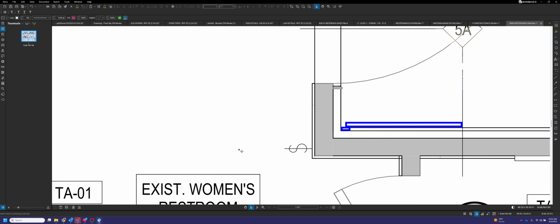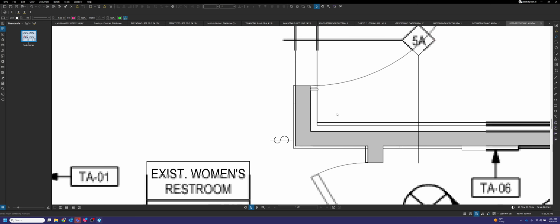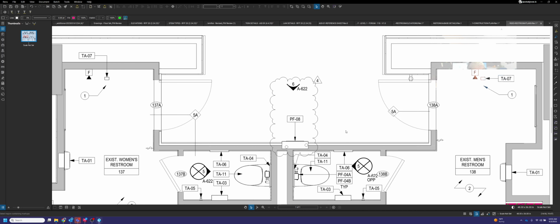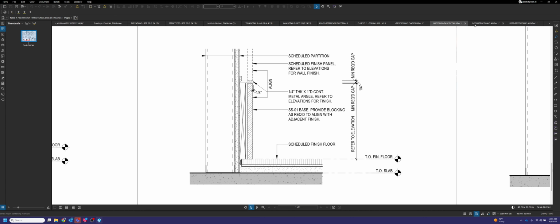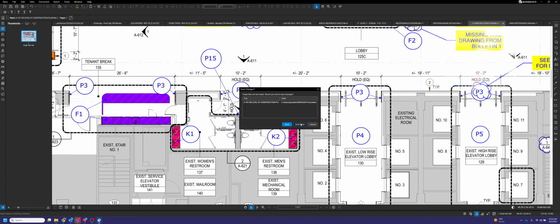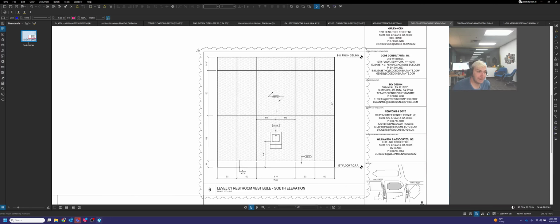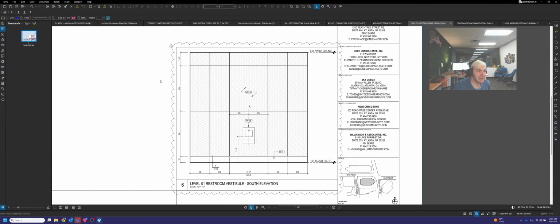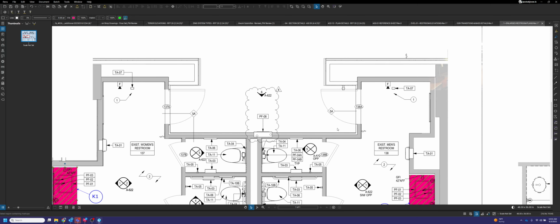Okay, so because we're using panel cleats there and we're using our full depth reveals at the corners and our 1/4 inch spline reveals between panels, that makes our lives a little bit easier. So let's go ahead and start by looking for other things here. We're going to look for dimensions to see if we're given any dimensions for these panels. It kind of looks like we're given at least a couple of them, but not enough to really have an idea of what we're dealing with here. Going back to this view, the plan view 2, there aren't really a lot of dimensions here for these panels.